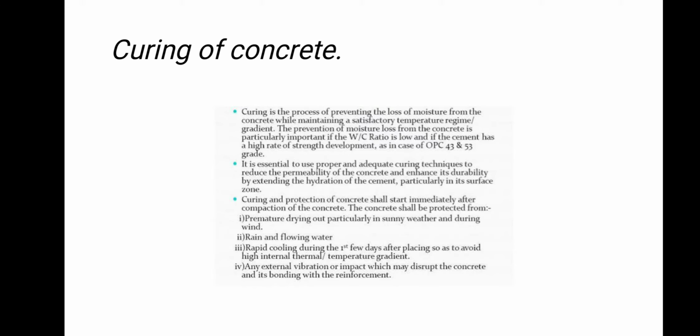Now, what is the meaning of curing of concrete? Curing is the process of preventing the loss of moisture from the concrete while maintaining a satisfactory temperature. The prevention of moisture loss from the concrete is particularly important if the water cement ratio is low and if the cement has a high rate of strength development.